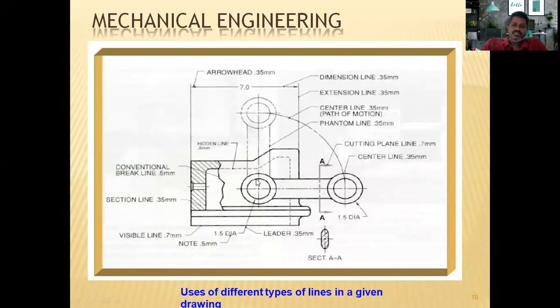And there are some surfaces which you cannot see. There are some edges of the component that we cannot see in our view. In that case, we need to represent those edges as a dotted line, as you can see here. So this is an edge inside this component that you cannot see. That line needs to be represented as a dashed line. So dashed lines represent the edges which you cannot see. Those edges will be drawn as dashed lines.